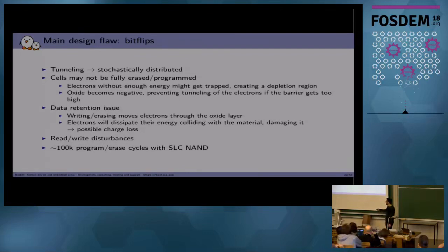For an SLC NAND, it's about 100,000 program and erase cycles. For MLC, it's much less than that. I haven't talked about MLC. It's a multi-level cell, when you put multiple bits in one memory cell. But it's not very stable.